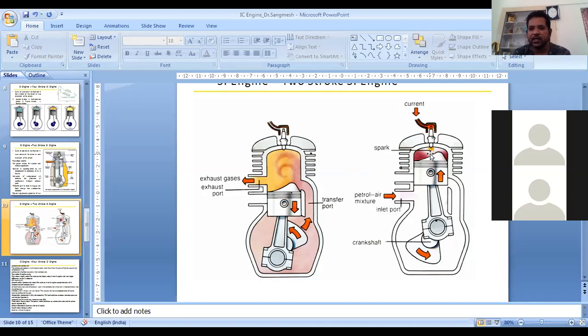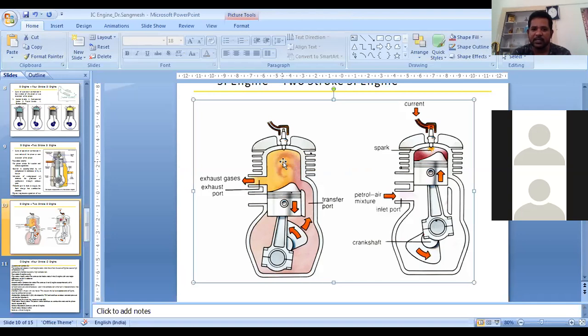So as and when it reaches the ignition temperature, the spark plug produces a spark due to the electric operation. So the power is going to be produced, as in the figure. Due to the expansion, the piston starts moving very rapidly from TDC to BDC, due to which it produces power. At the same time, all the flue gases are exhausted to the atmosphere.